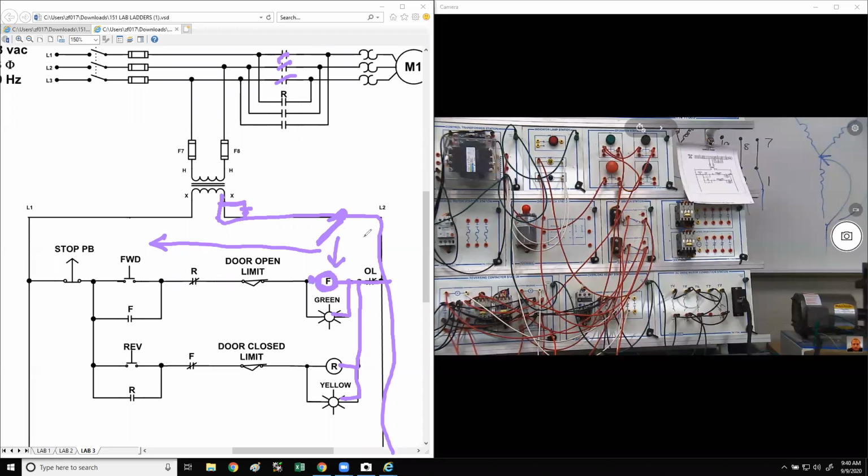You go to the stop button? Huh? You want to check from the output back. The reason is, if you say maybe the stop button's not working, you check the stop button. Or if you start here and you start working yourself this way, maybe you'll find the problem, but you're going to end up scattering all these different directions. That's why it's output back, not back output.